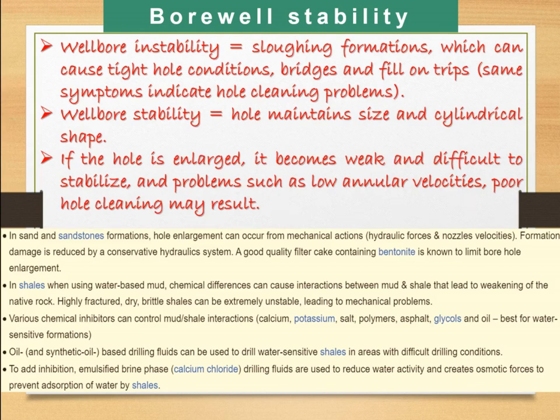Another important property is borehole or wellbore stability, because wellbore instability means sloughing formations, which can cause tight hole conditions, bridges and fill on trips. The same symptoms indicate hole cleaning problems. So wellbore instability often causes even stacking. Okay. On the contrary, wellbore stability means the hole maintains its size and cylindrical shape because there is no collapse.